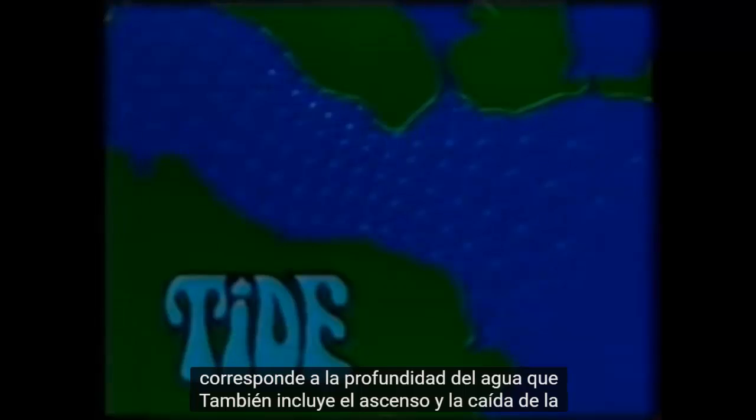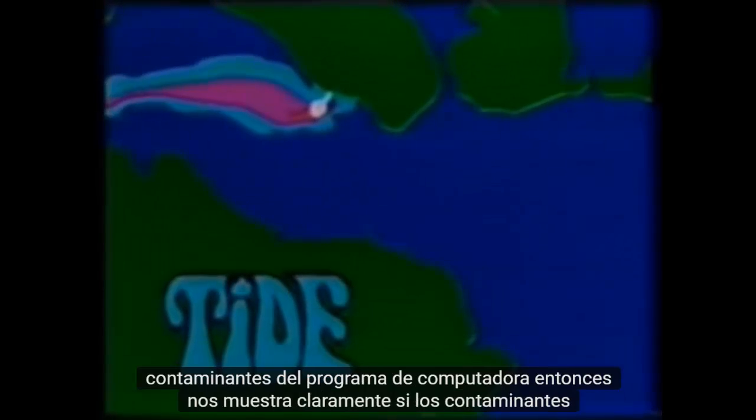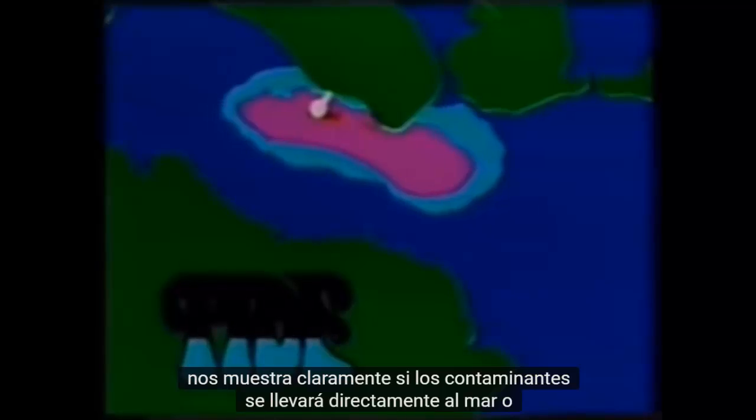Finally, one more example, also from Southampton. This program is designed to study the dispersion of pollutants deposited in tidal waters. The finite element mesh here corresponds to the eastern Solent extending to Portsmouth, and the thickness of the elements corresponds to the depth of the water. We also include the rise and fall of the tide and insert a specified outfall of pollutants. The computer program then shows us clearly whether the pollutants will be carried straight out to sea or whether tidal effects will cause dangerous concentrations to build up near the beaches.